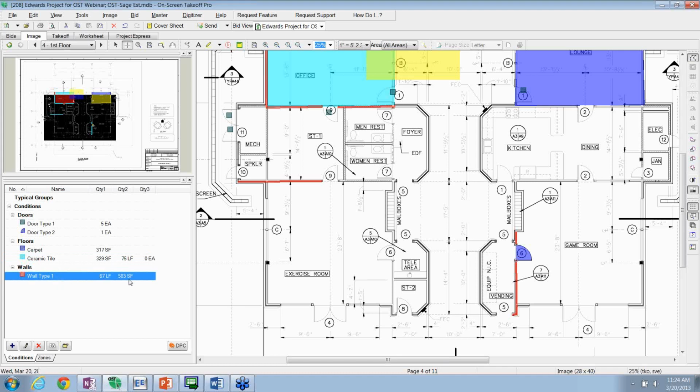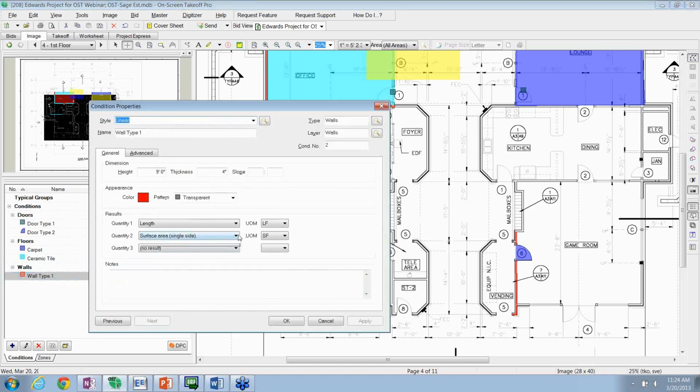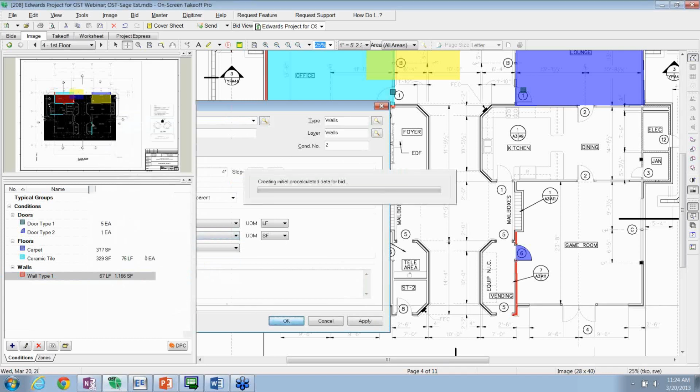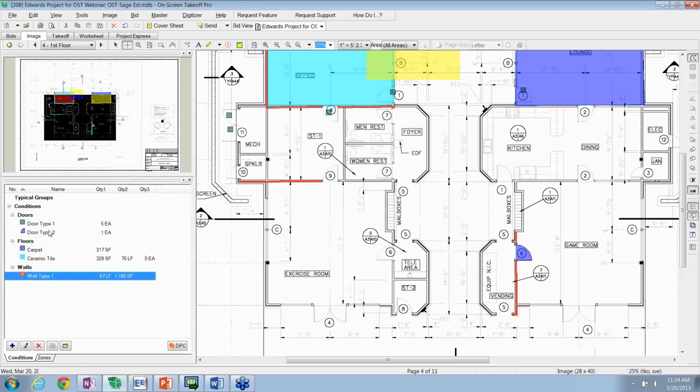In this case, 67 linear feet. Here's my total square footage. But if I come back here and say I really want it on both sides, you'll see that that'll double. But as I use the attachment feature, different from the count, as I drop that in, it'll instantly pull out the supporting square footage of that 3080 door.